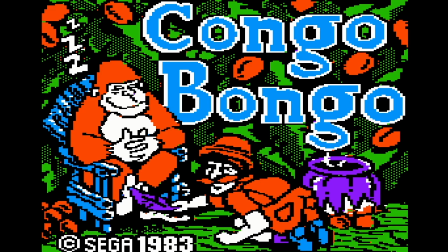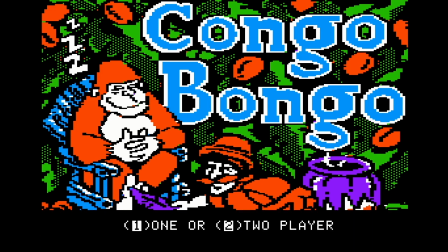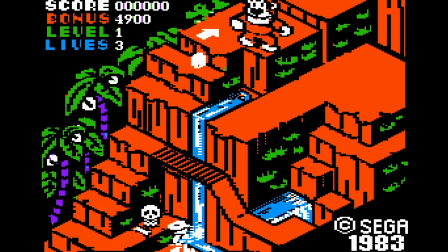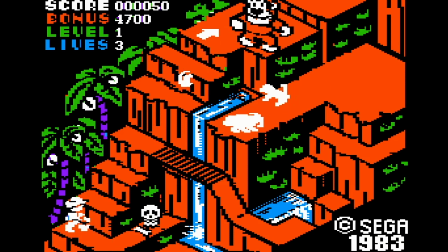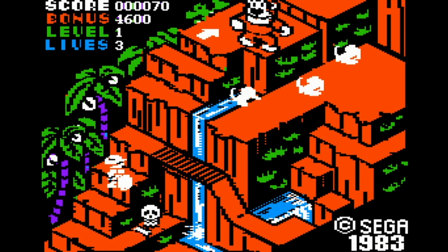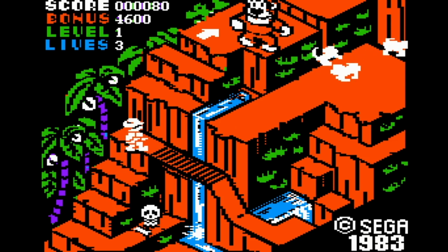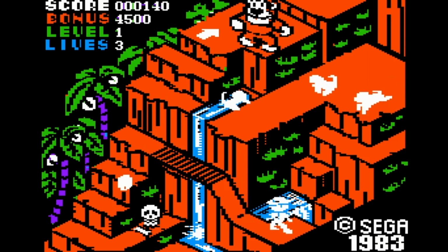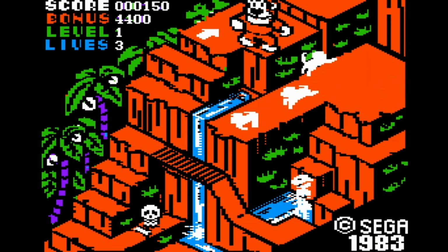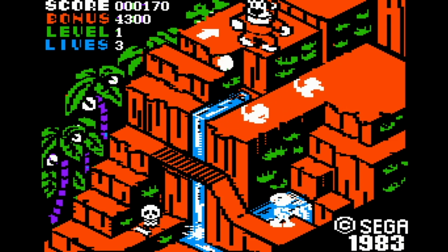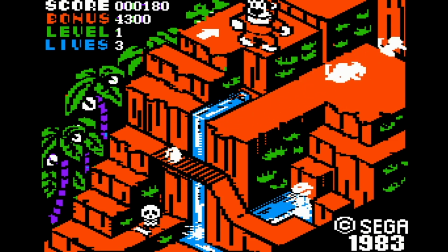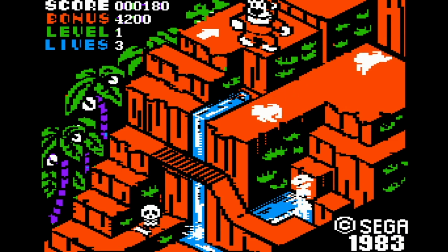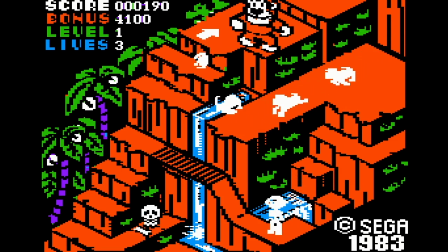High-res is also based on text mode, but uses 8 bytes per 7 by 8 pixel region instead of just 1. This provides individually addressable pixels, but consumes a lot of memory by 1977 standards, 8 kilobytes. The Apple II high-res mode can display 6 colors: purple, green, blue, orange, black, and white. The vertical resolution of high-res mode is 192, which is simply 24 times 8, but the horizontal resolution is complicated. There are 280 black and white pixels horizontally, but color requires 2 bits per pixel, so there are effectively 140 color pixels.